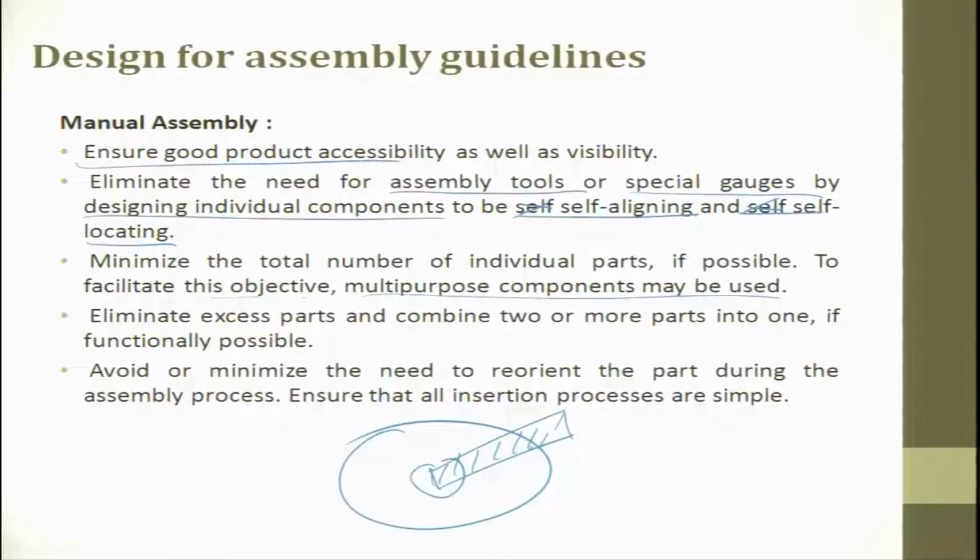So, first of all you try to see whether these two materials can be made of a single material, and if there is nothing big that is going to bring a difference when it is made of a single part, then they say please go for a single part. So, eliminate excess parts.